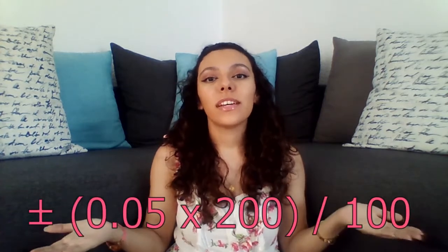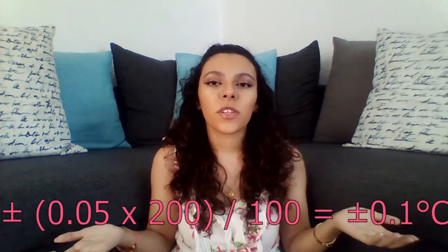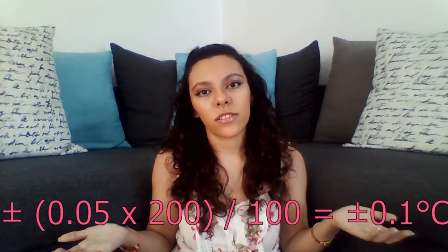Sensitivity is the smallest absolute amount of change that can be detected by a measurement after the resting state has been reached and is given in percentage of the span. Retaking the last example of the temperature instrument, again, plus minus 0.05%, we do the same operation we did to calculate the dead zone. And this gives us plus minus 0.1 Celsius, which means if temperature changes plus minus 0.1 Celsius or more, the instrument will be able to detect it and adjust its output to display that change.